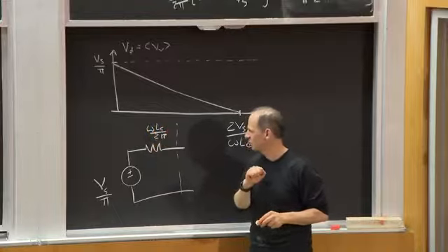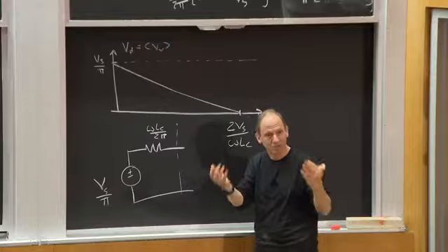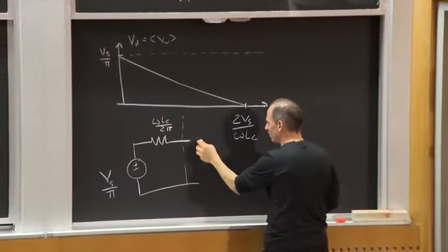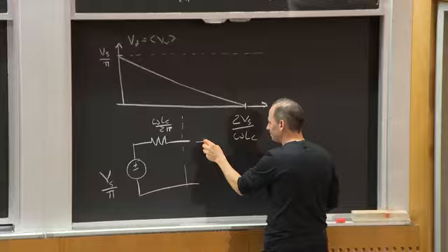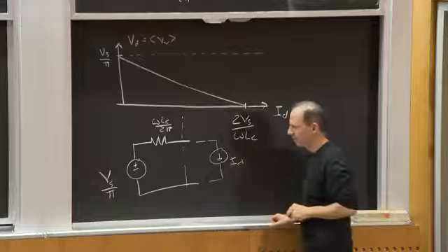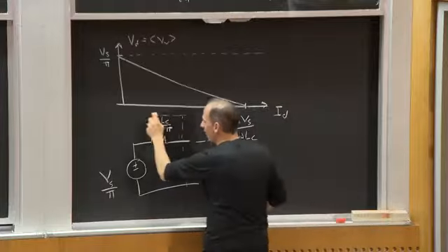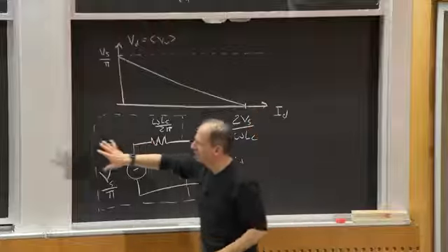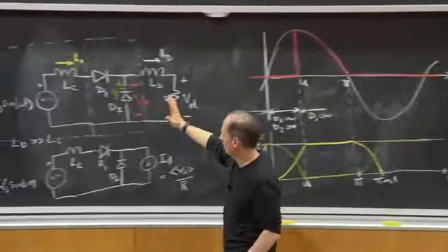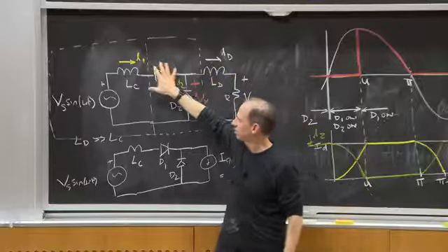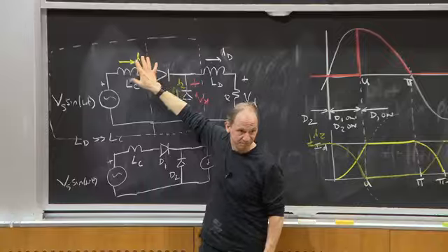So omega LC over 2 pi has the right units to be a resistance, okay? And then I could connect this thing to effectively my inductive filter, or more simply, my load current ID, okay? So this is not a bad model for how, looking back from the DC side, or looking back from the side of this filter, this thing will behave on average.